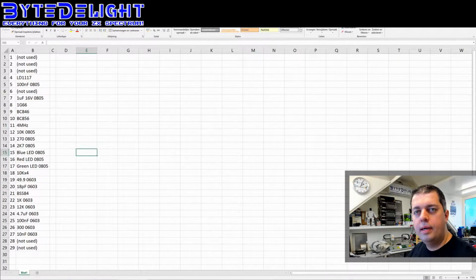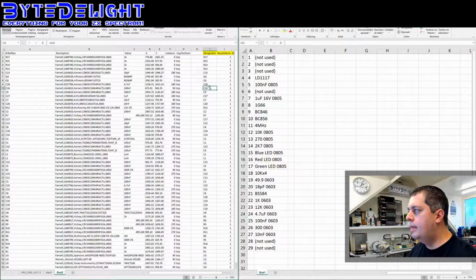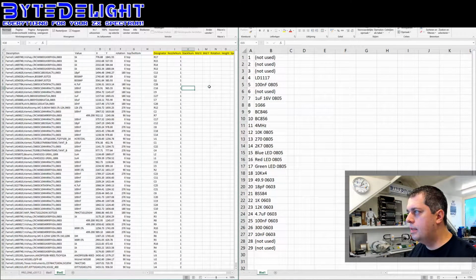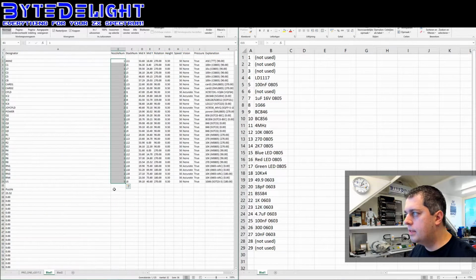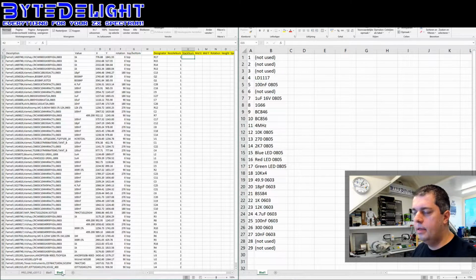So now we can compare this file with the file that we are editing, and we can use the correct stack number or reel number. Yeah, stack number, but there should be an L that stands for left, because the TVM802B pick and place model has two reel systems, a left and a back one, but we only have the left reel system.